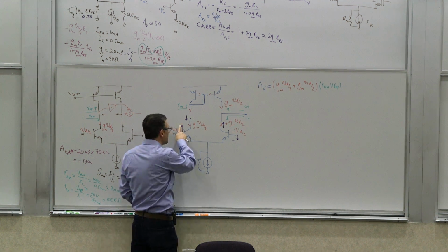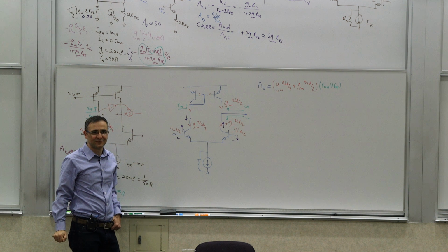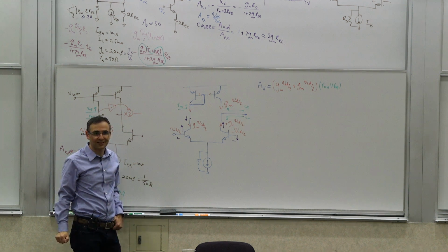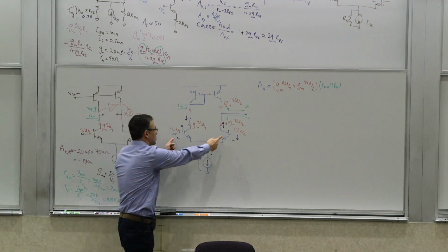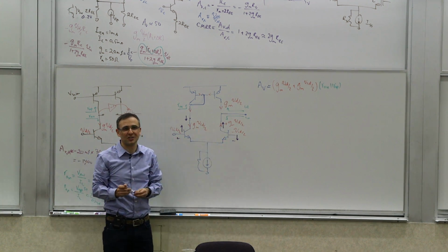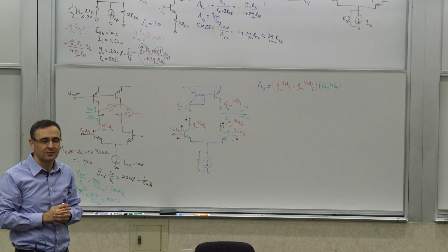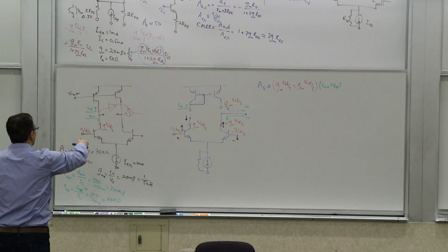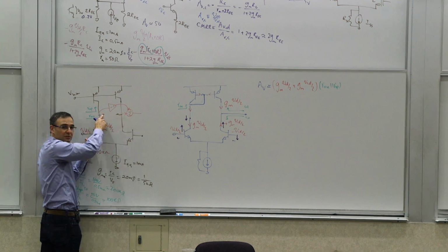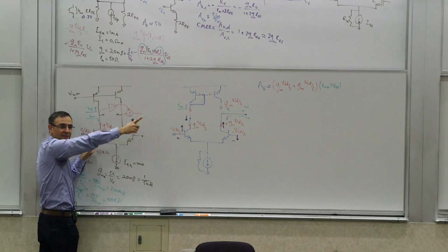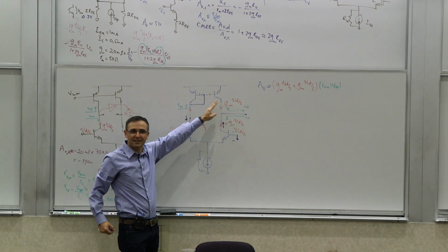So remember, this is going up, this is going up. So this is non-inverting, the way I've drawn it. Now, you can easily turn it into an inverting stage by switching these two inputs. So it's not fundamental, but the way we've drawn it and defined it, that's non-inverting. It's like taking the output from here, right? This is also non-inverting, because it was inverting from here to there, but this is the opposite polarity. So that's where your inversion, that negative sign, is coming from.